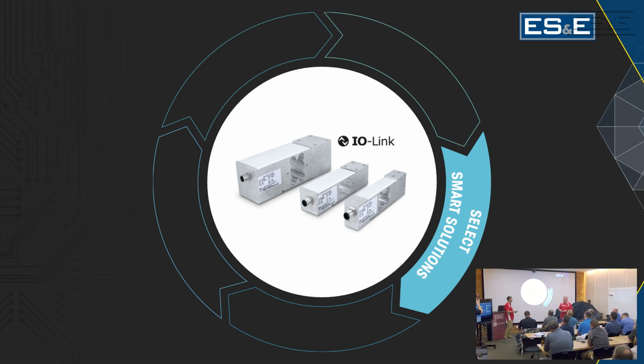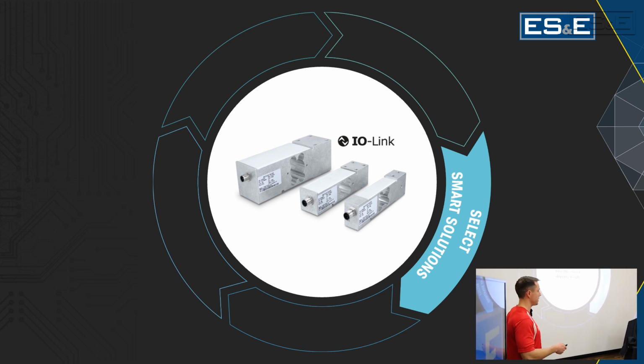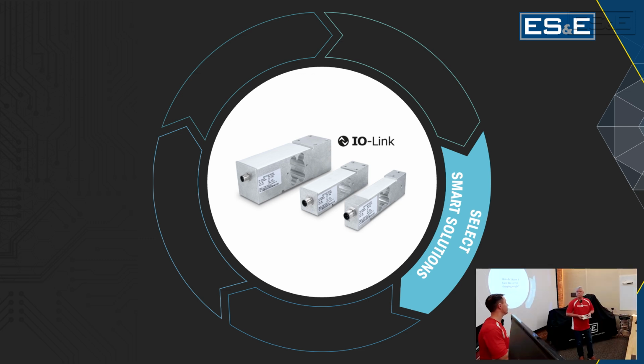How about an integrated system that we can send all that data back to, some type of control system? So the control system is going to be able to get the weight. It will, and you're right, the operator places the plate on the weigh cell, and then we'll get some type of visual feedback to let him know if it's correct. So like an HMI or a stack light or something along those lines? Yeah, whatever you choose, or we can do both. So it'll know if it's a fail or a pass. Obviously, you can get green for pass and red for fail. Awesome, that sounds good.